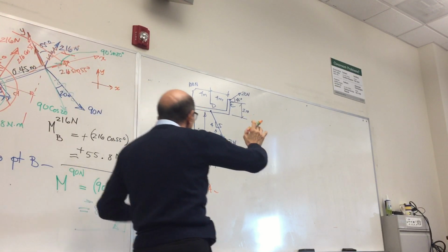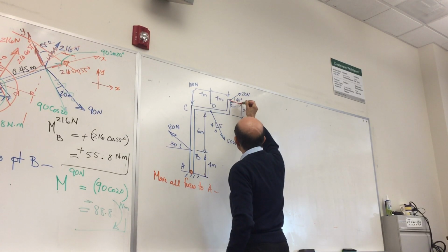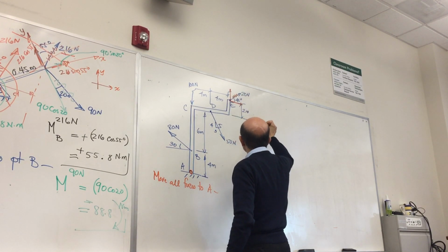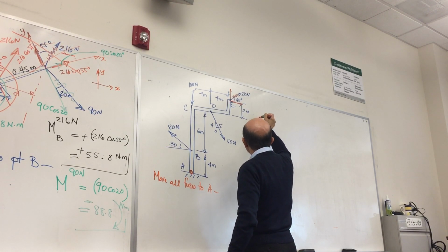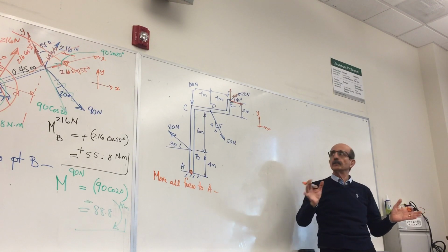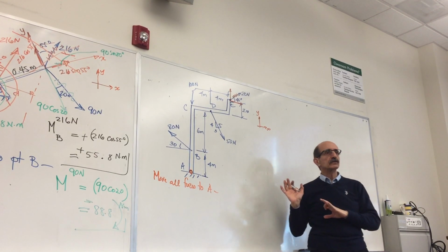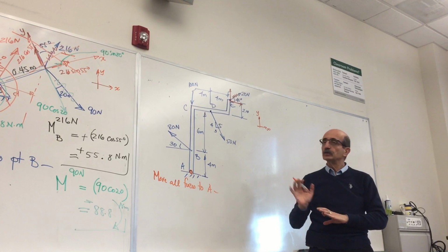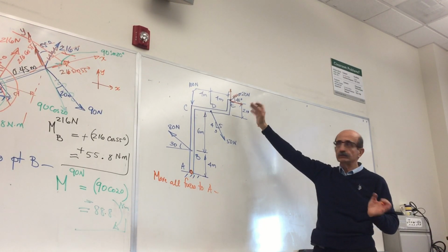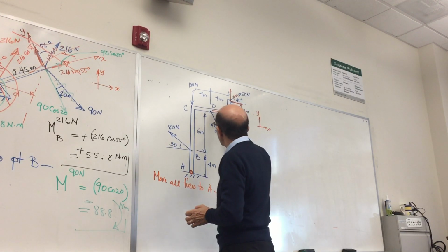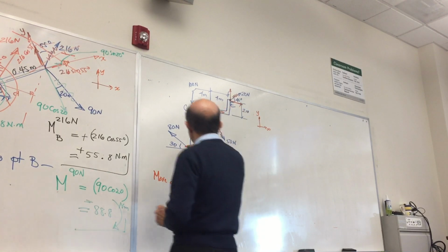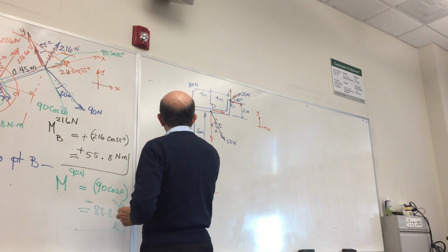Anytime you have any force which is not acting along the X or Y direction, it's always best to resolve the force into its components. Because the action of the sum of the components is the same as the action of the original force. So I will always replace the force with its components. Okay? So let's do that.